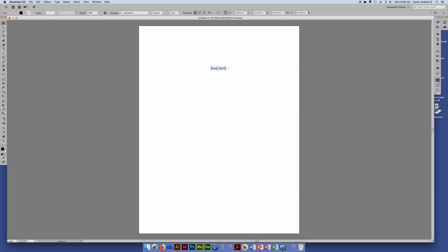And then this is the actual width and height of your object. I'm going to undo a bunch. Right now it's set to not constrain proportions. You can see that little link icon with the slash through it. I'm going to click it to make sure that it does constrain.